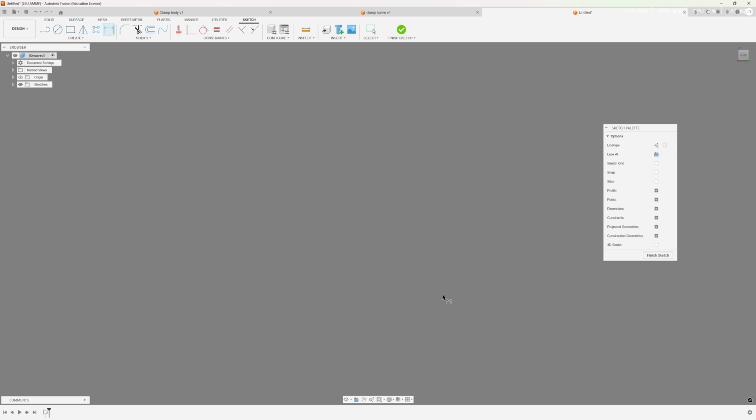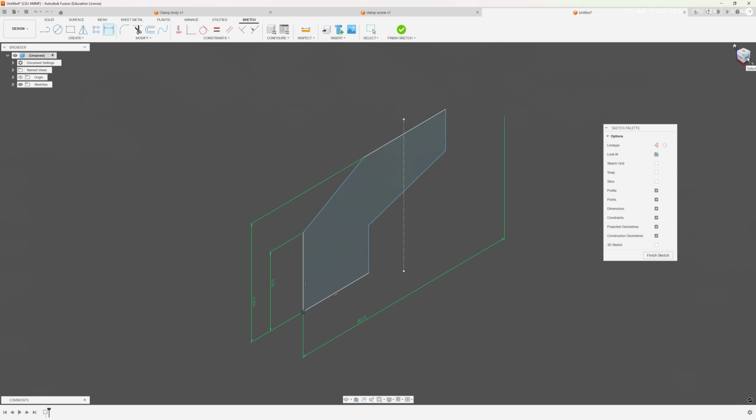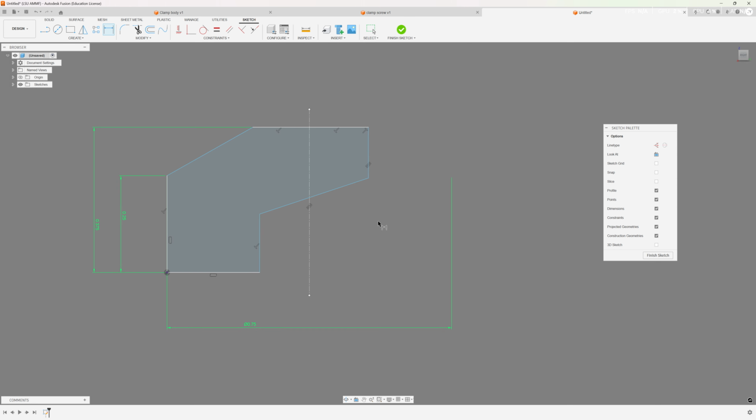Did I give that the wrong? Oh yeah, I forgot the point. That was 75 inches. 0.75. Right, go home. I've lost where I am. All right. Yeah, if you lose your sketch, you can always hit the go home button. Now, since I'm using a center line, when I selected the 3/4 feature, it gave me an overall dimension of 3/4, which is very convenient, so I don't have to do the divided by 2 function that I was doing previously.